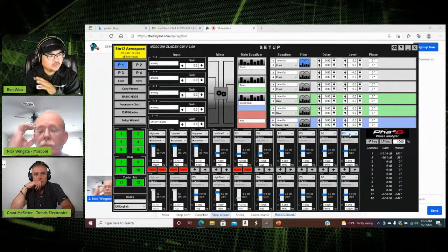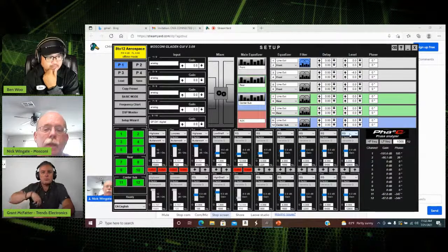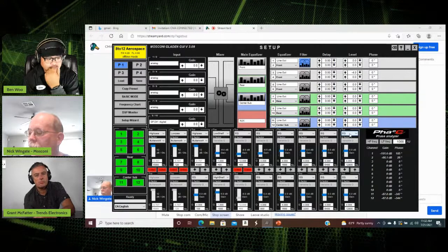Could you backtrack one step? What are the three criteria before even getting into time delays? Number one, you've got to make sure that every single solitary speaker is playing at the exact same level. That is number one. I cannot stress that enough.